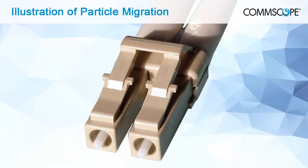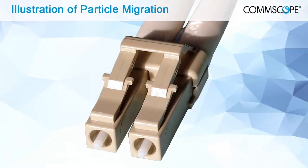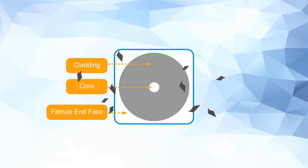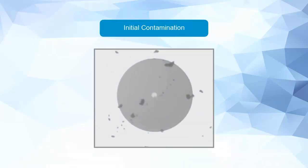Before we continue further in this lesson, we need to visually see the result of contamination on the end face of the fiber connectors. It is not only contamination on the fiber core that is important. Debris elsewhere can also cause problems because when you mate two connectors together, the particles, especially larger ones, are very likely to explode as the pressure is applied to them. This graphic shows an image of the end face of a connector that had some fairly large pieces of debris on it, taken using a 400 times microscope.